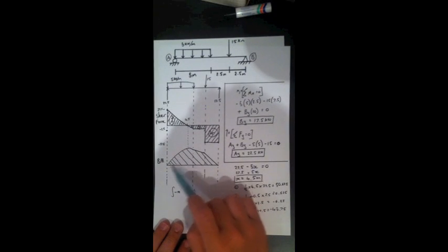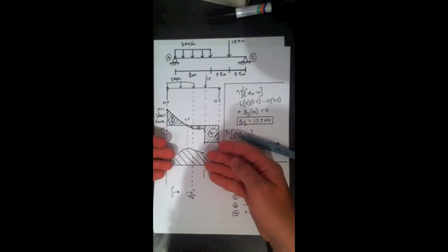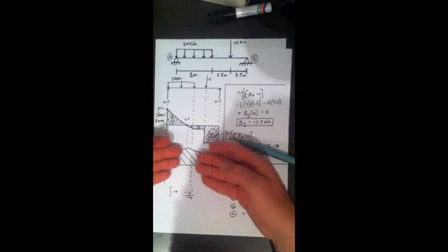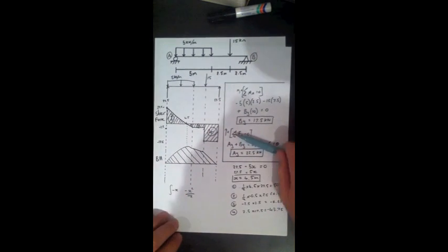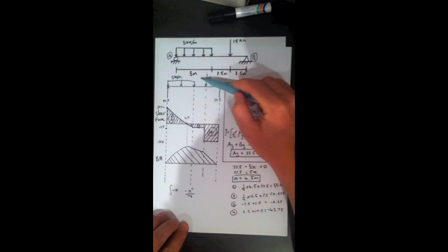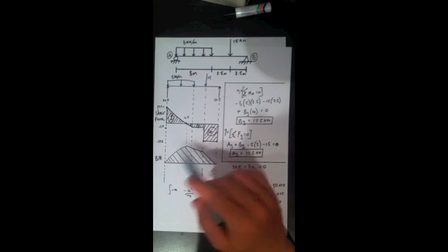So what should end up happening is your bending moment should basically look like the inverse of how your beam will bend. If you took this and flipped it over, you'd have the curve going down here, then your straight line, and then your other straight line. For me, it makes sense. It's a quick way of making sure that you're on the right track with your bending moment diagram.